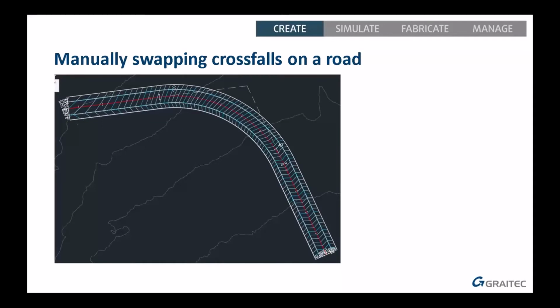You can use that super elevation table to work on small site roads as well that don't use these standards. So, for example, here where the lie of the land makes it better to have a single crossfall after the bend, for example. Here's the normal crossfall. I've not designed any transition curves, so there's no tables to look at. We haven't got any design speeds on there. We just want to set a single crossfall after a set chainage and transitioning over a set length.